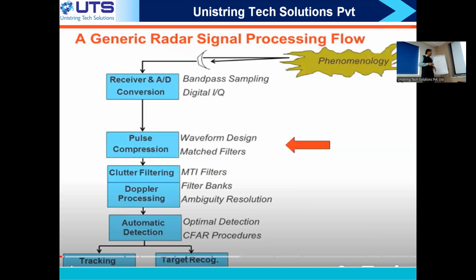Okay. So detecting a target is one thing. Then next one, tracking, is nothing but a long-term observation based information to the user. Okay, at this time there is a target, at this time there is a target. If you show that, that is one thing. Track is nothing but I make multiple measurements and it gives more confidence. Do you agree or not? For example, false alarm is there. Will it come like a track? It won't come, because false alarm is a random phenomenon, it just comes and goes.